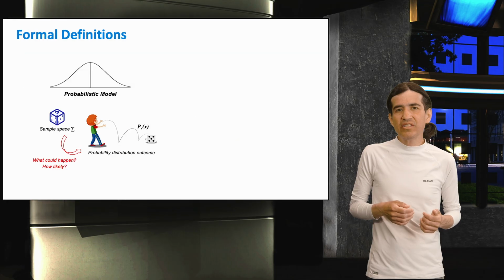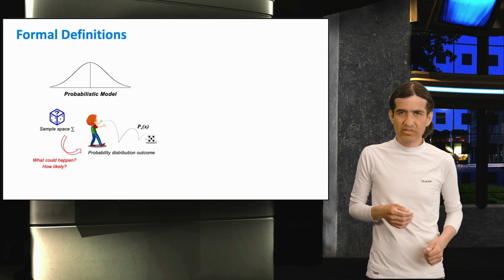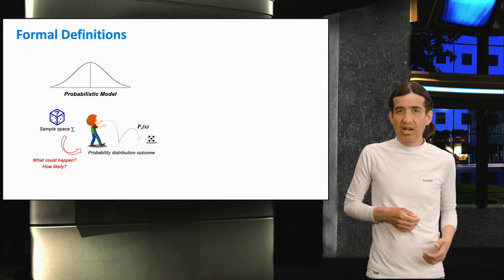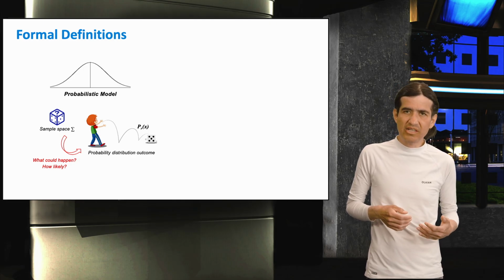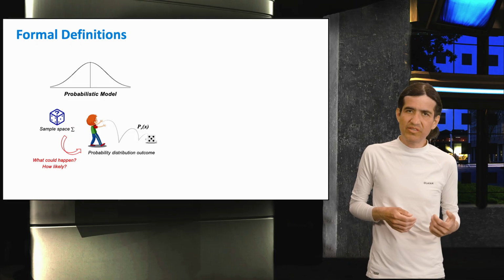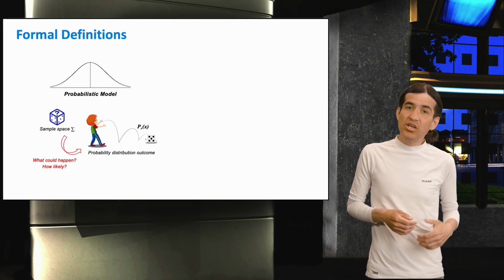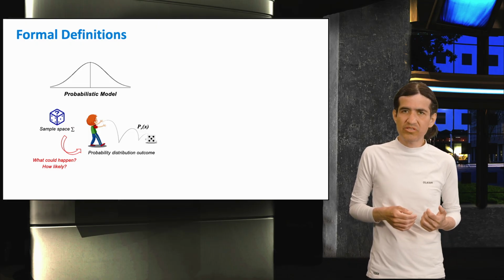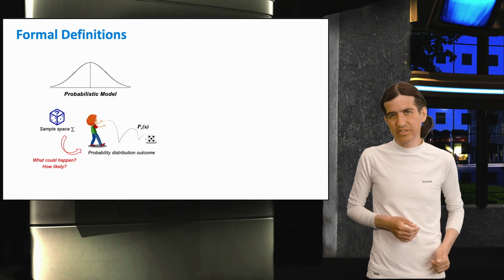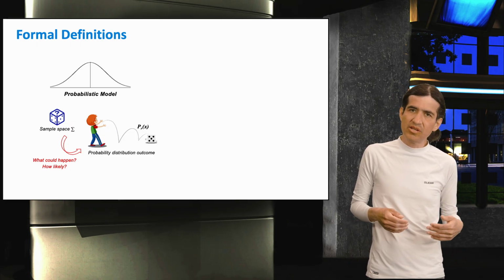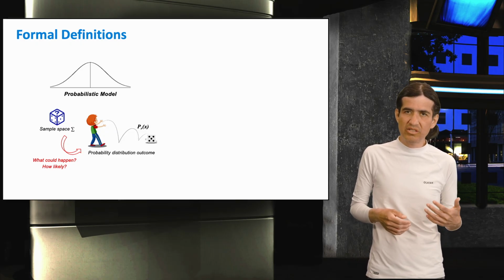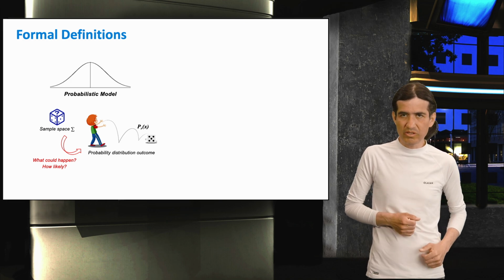Let's now revise definitions of interest for this lecture. A probabilistic model represents uncertain inputs, for instance, data concerned with random variations of demand and generation, using probability distribution functions defined over a sample space, producing outputs that are also probabilistic, like voltage, current, dispatch, power transfer, or losses in the distribution or transmission network.